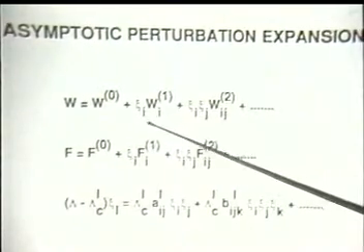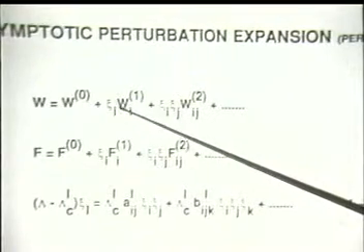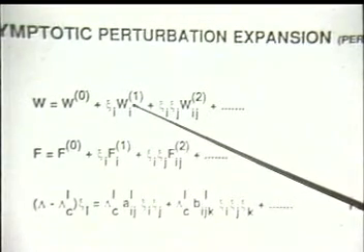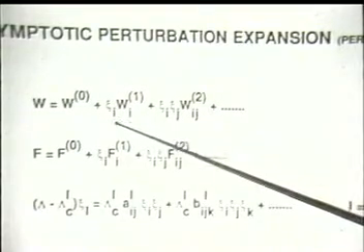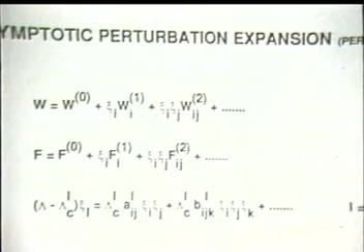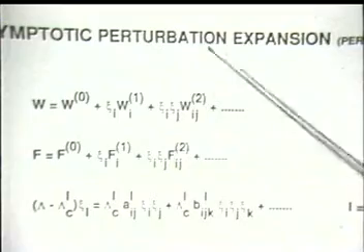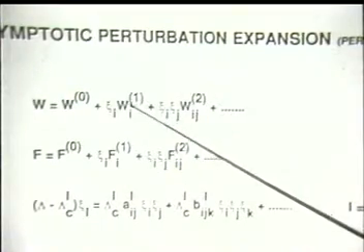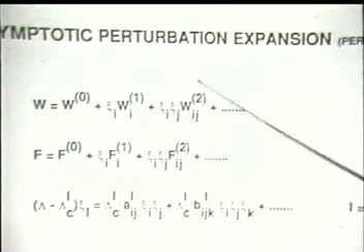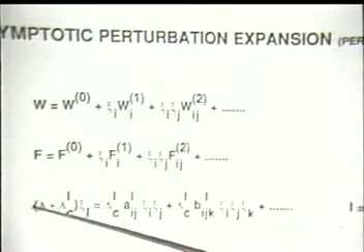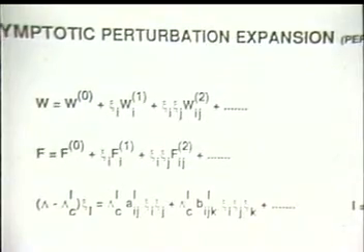And the modification here is that since there is more than one buckling mode which is active, we sum over them. So essentially, the repeated lowercase indices here imply summation. The consequence is that you also have to sum over the second order field. So essentially, you end up with many of these, as many as there are nearly simultaneous modes, and then that much more there. Here is the well-known form that is used to describe the load deformation behavior.